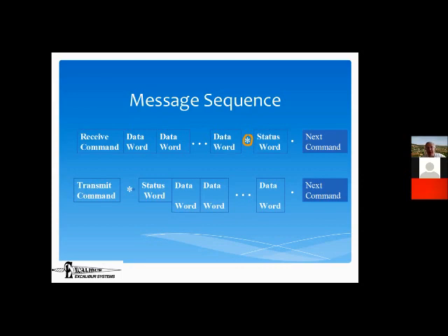Now, this dot here represents the intermessage gap time. We've just completed an entire message, and we're now ready for the next message. And so the time in between those messages is called the intermessage gap time. And there's a minimum of like 2 microseconds. There's no maximum. And if I don't happen to have any rush to send anything, then I can just not send. The bus controller can just decide to have some quiet.